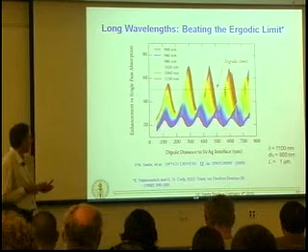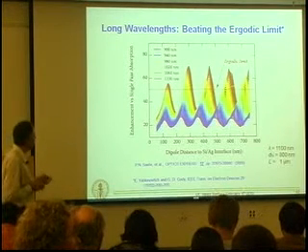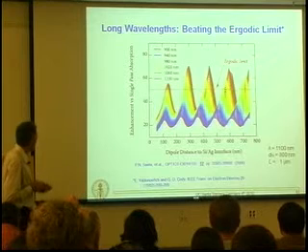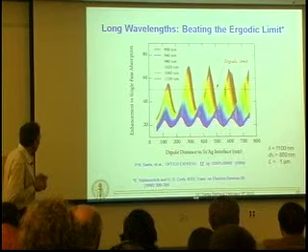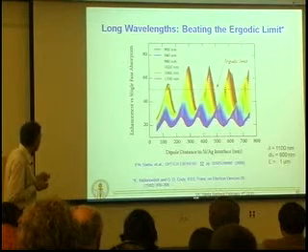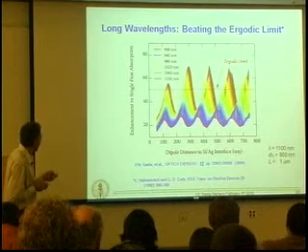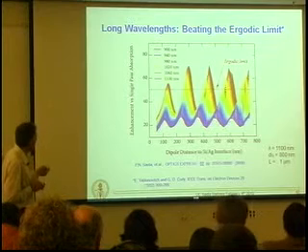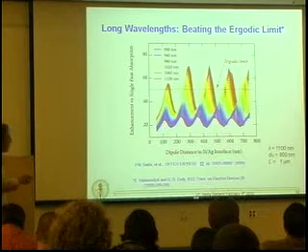So a carefully designed non-random structure has better absorption than a random structure, and so this is the 4n squared factor of 50 for silicon. And if I put a dipole scatterer at some distance from the metal semiconductor interface, say 100 nanometers away in the film, or 250 nanometers away, or close to the surface, I can enhance the absorption in this optically thin region of the cell relative to a randomly textured sheet.